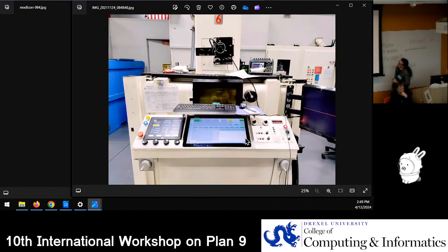Now what we have is an HMI all the way off to the left that deals specifically with the vacuum system. The vacuum system is those two colored buttons in the upper left-hand corner. Blue means that you're under vacuum, and yellow means that you're vented. Those two buttons, which just operate some code inside the PLC, completely remove the need for the operator to stand there and stare at the machine and index a knob. And of course the boss loved that, because now they can do more work while waiting for the vacuum.